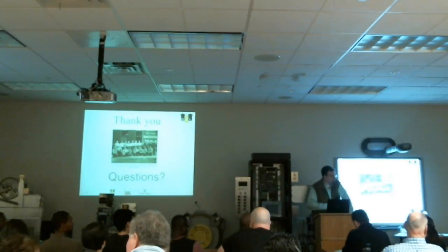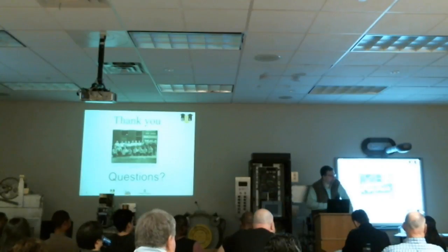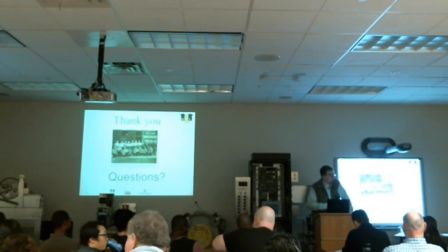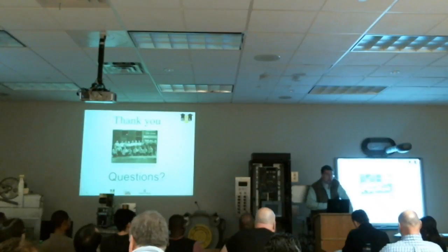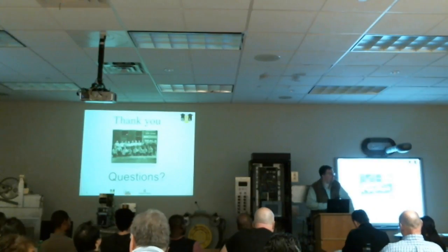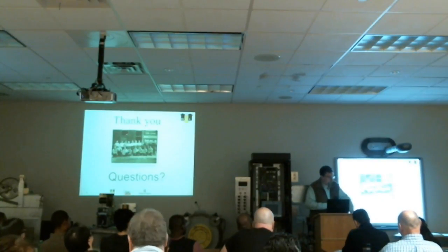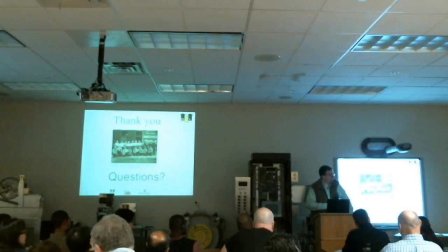What type of service is GL going to be offering these customers that get the fault monitor? Let's say on the legacy relay logic control, they're going to be getting back their diagrams marked up with instruction sets on how to wire it. The idea is, get a set of prints, we will mark them up: number of modified wires required in the hoistway, number of wires required from the car.